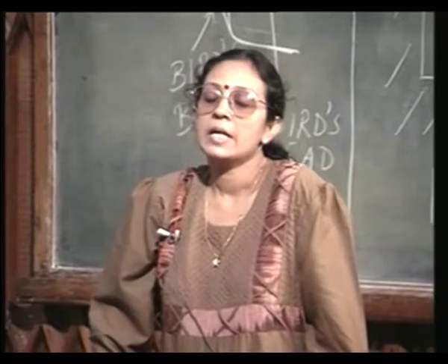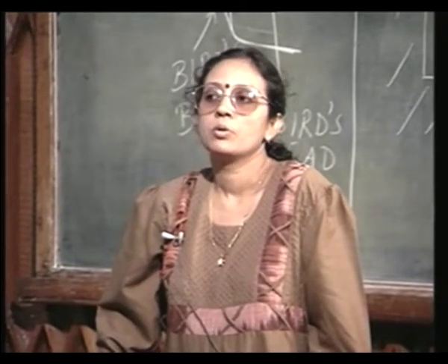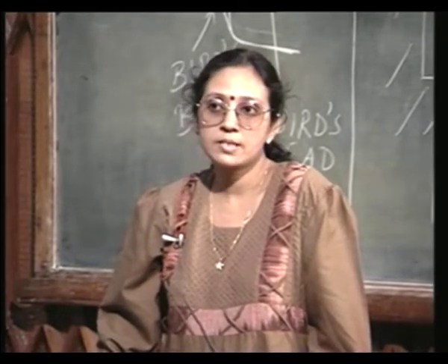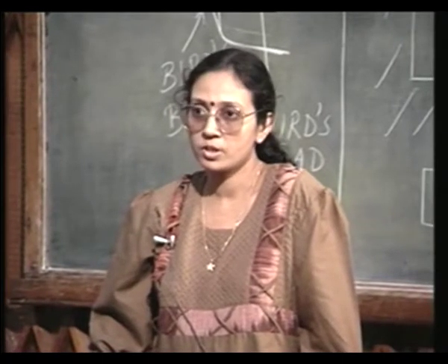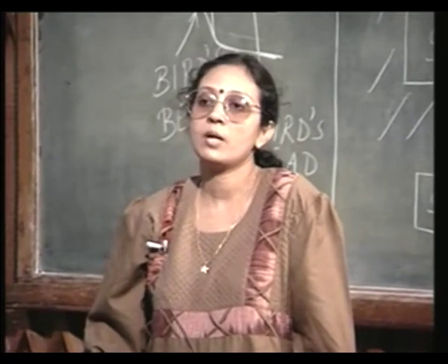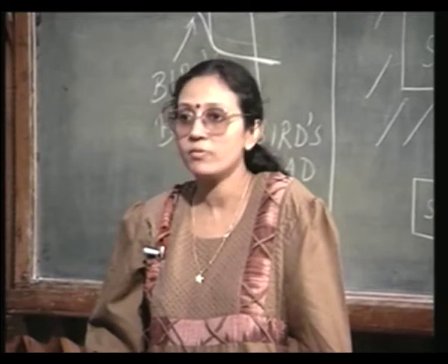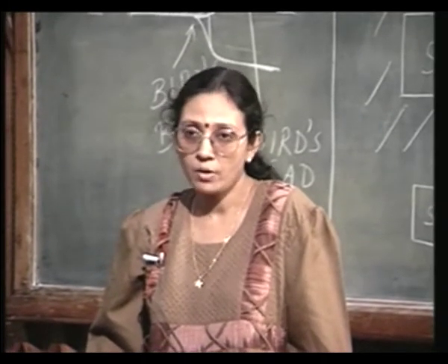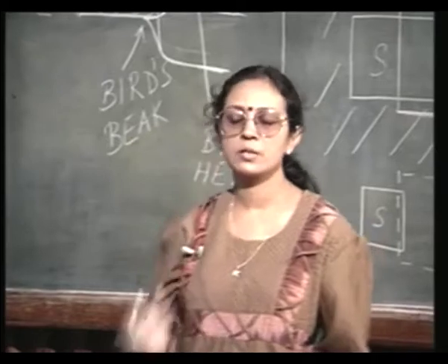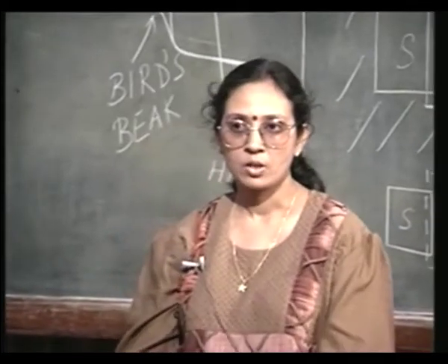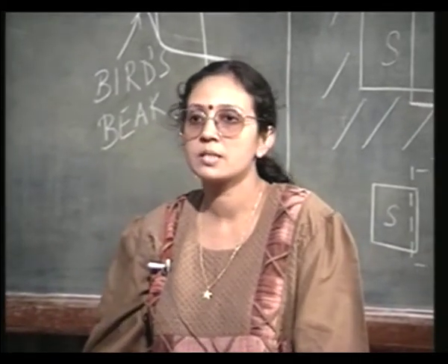Okay. When I discussed the low cost technique in bipolar junction transistor, I said that if you have recessed oxide, you are going to have this bird's beak problem. However, in case of bipolar junction transistor, it was not very serious, because you are only using these regions for isolation.